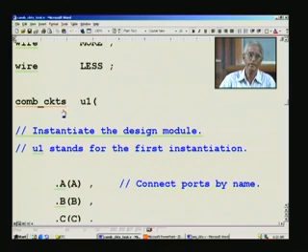So, when we call, what it means is when you convert this into an actual working circuit as an IC chip as such, then this circuit will actually function because of this statement, right. So, you have to instantiate here. Whatever is the design module, you have to call that module, that is known as instantiation here, and you just put that particular design module name, that is all. Are you clear about it?